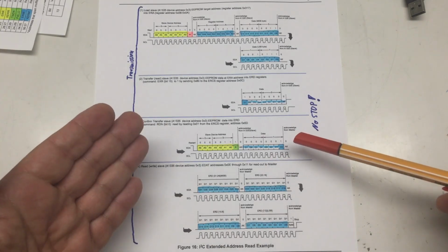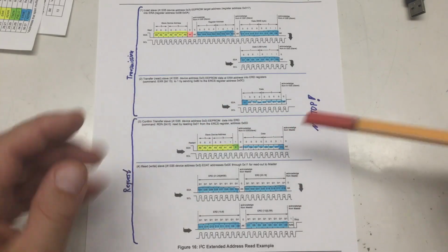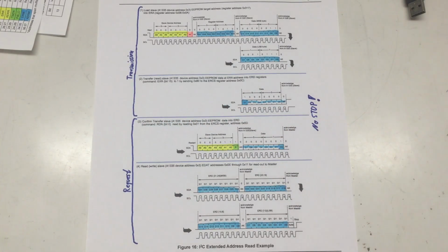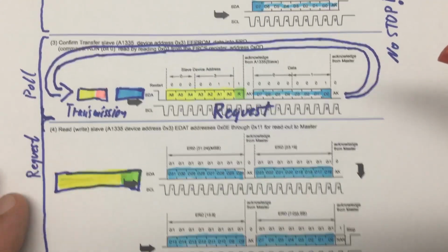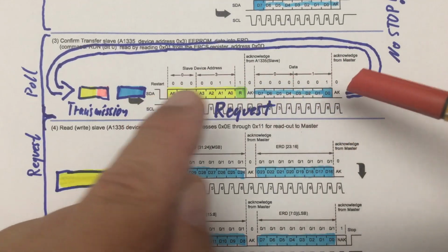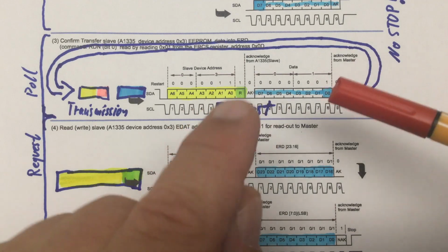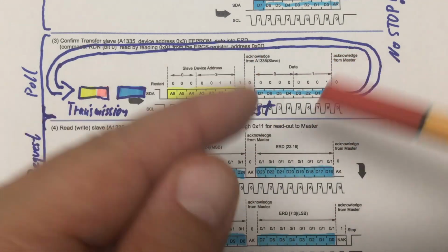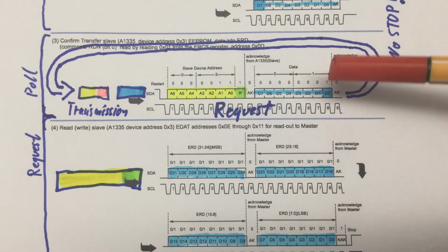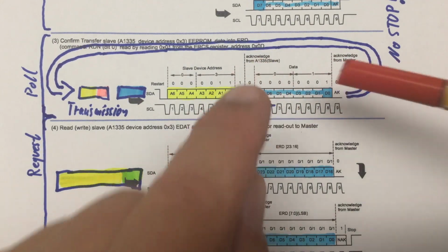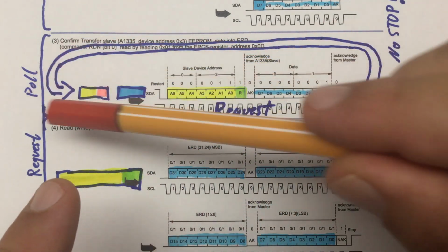And the datasheet says also you should not simply do here a static wait, but you should poll for that single bit here. Meaning, after we finished our transmission here, we only request a single byte from the chip, and that would be, of course, the least significant byte of the extended read control and status register, and then we check if the read done bit in that byte is set. If that's not the case, we have to go into a loop.